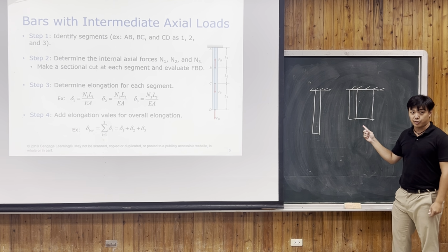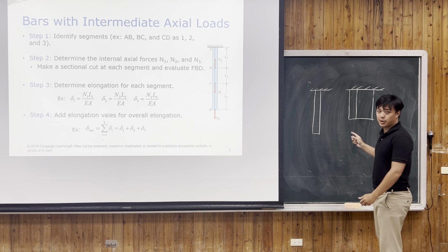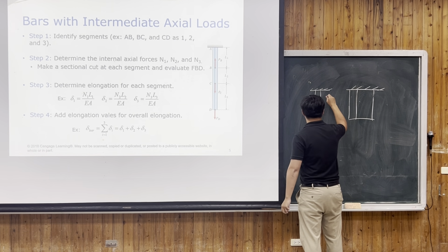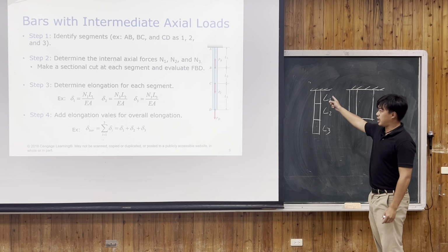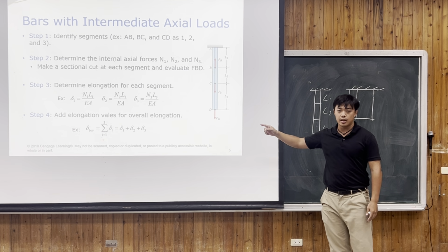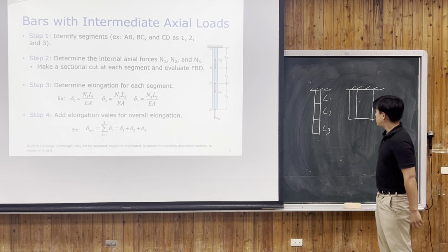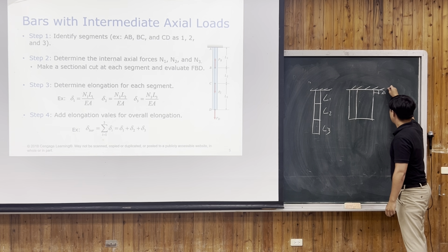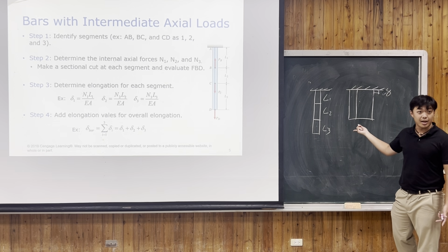Do you guys know this kind of question? Haven't? So for these kinds of questions, you can see the elongation values. We have to add up each segment and we get the overall elongation. And for the parallel kind of questions, they will have the same elongation.